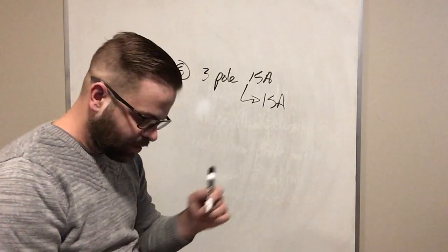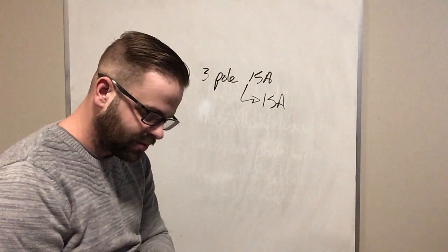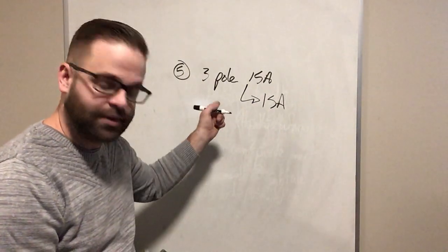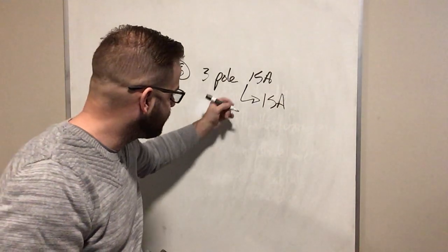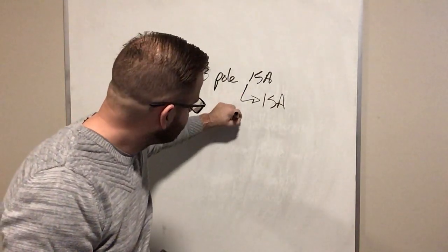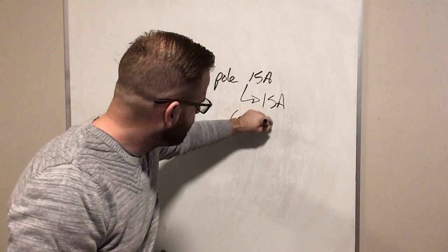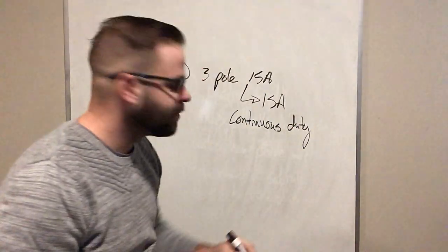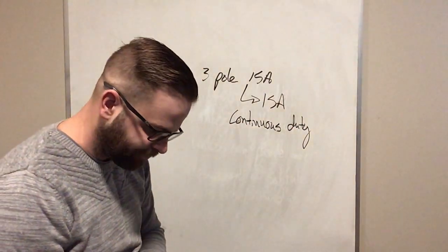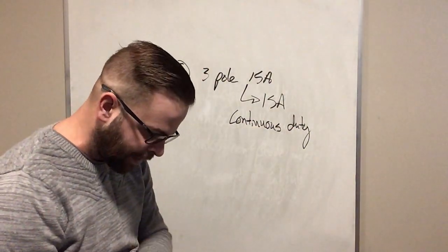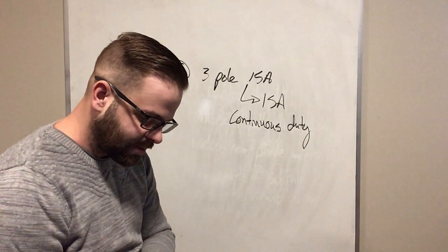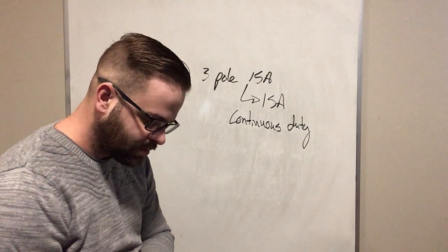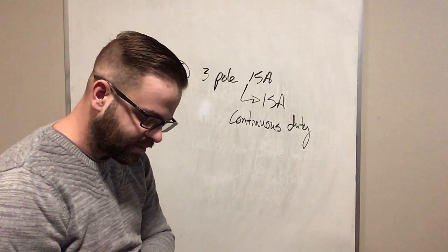So we have a breaker that's running at continuous operation at 100% at the ampere rating of the device. So 15 amp rating, runs at 15 amps. It's classed for continuous duty. Typically they're continuous duty at 80%, which is in the next portion. It says continuous load as determined from the calculated load shall not exceed the continuous operation marking on the fuse, switch or circuit breaker.